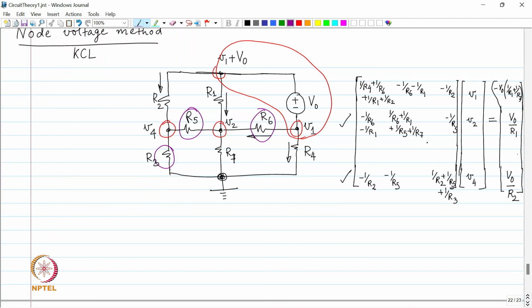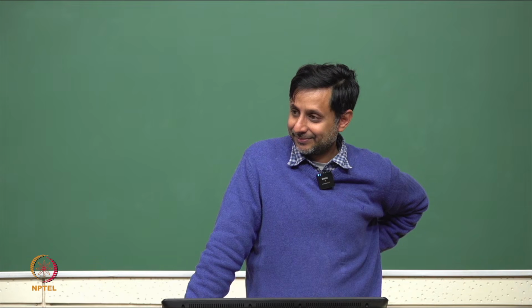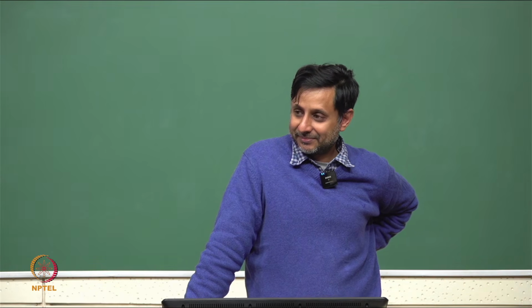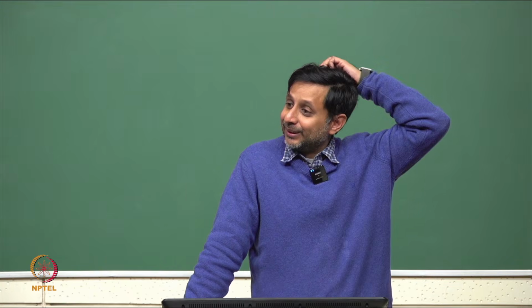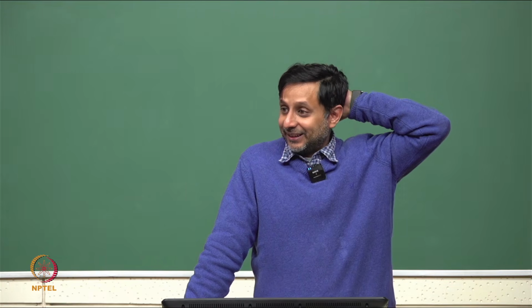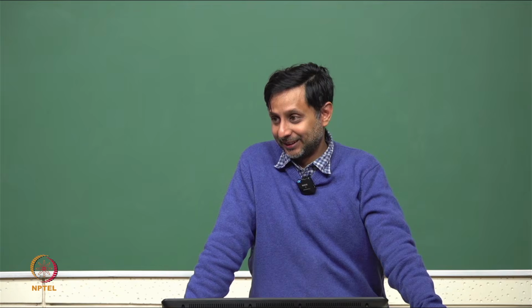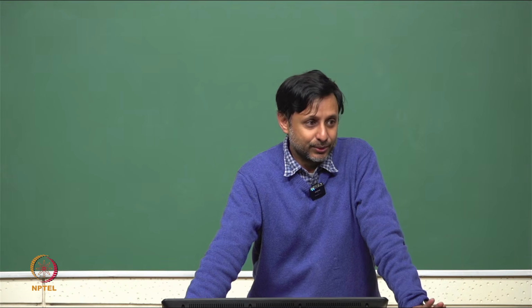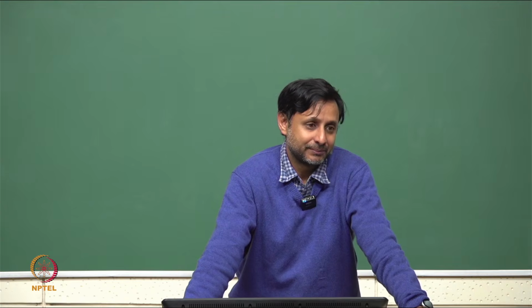Fine. Any questions? Otherwise you will end up with a KCL with only current sources, and that is illegal. You can't have a KCL with only current sources. You can't have a KVL with only voltage sources, you can't have a KCL with only current sources.